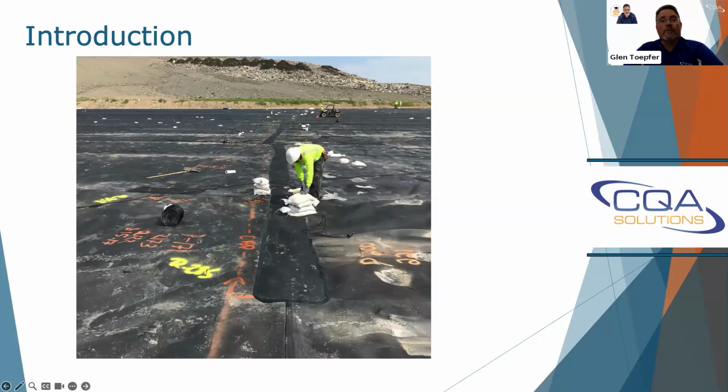So we went back through some of our projects. This particular project, I think we had about 1,500 lineal feet fail. It was a 15 to 16 acre project. And these are all fusion wedge welds, by the way. And so there was an astonishing failure amount on this project.